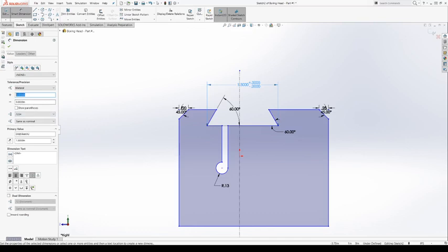At some point in time, I don't think that we have really dealt with them very much, but you will see something like this. So this is 1.5 inches plus 1 thou plus 1/2 thou. Right? Pretty weird. But this is an actual way of dimensioning. So when you have fits, this is a very, very common way of dimensioning things, in fact.